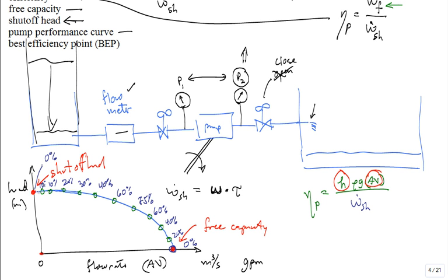You know what I'm doing? So along that curve, that's our performance curve, you could identify the point of operation which would give you the best efficiency. Don't you love this about mechanical engineering? It's just all so straightforward and simple. It's like the mechanical engineers that work with pumps, it's like, that's the best efficiency point right here. It's where you get the highest efficiency. How would you determine it? Typically, experiments. You have your pump and you design your impeller and you go out and measure it.